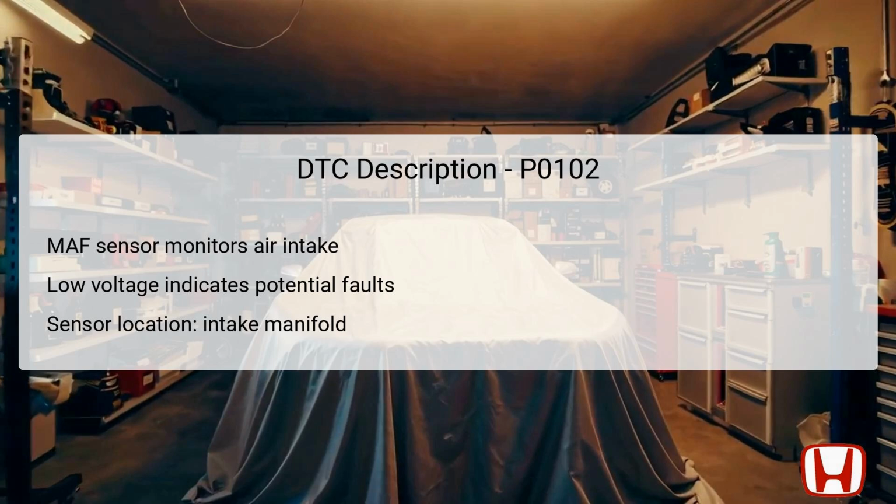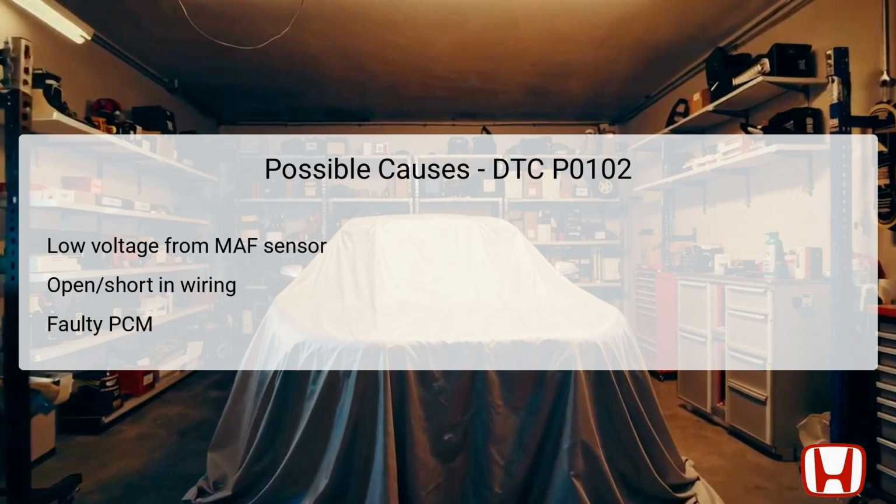This situation requires immediate attention to prevent further engine issues, and the verification of the issue must be completed first to confirm the failure's persistence. Several factors can lead to the appearance of DTC P0102. A primary cause is the MAF sensor outputting low voltage due to internal failure or degradation of the sensor itself, which could be attributed to age or contamination.